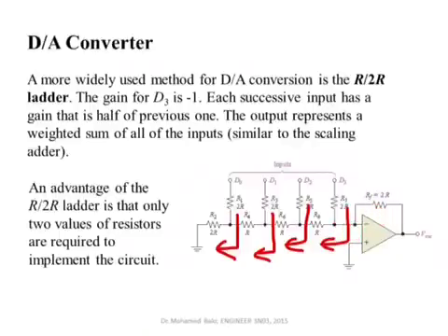And you will see, depending on whether D0 is 1, or D1 is 1, D2 is 1 or D3 is 1, the equivalent Thevenin voltage scales up. So here it's going to be V reference over 16. If you apply a voltage of V reference here, the Thevenin voltage seen at this point is V reference over 16.